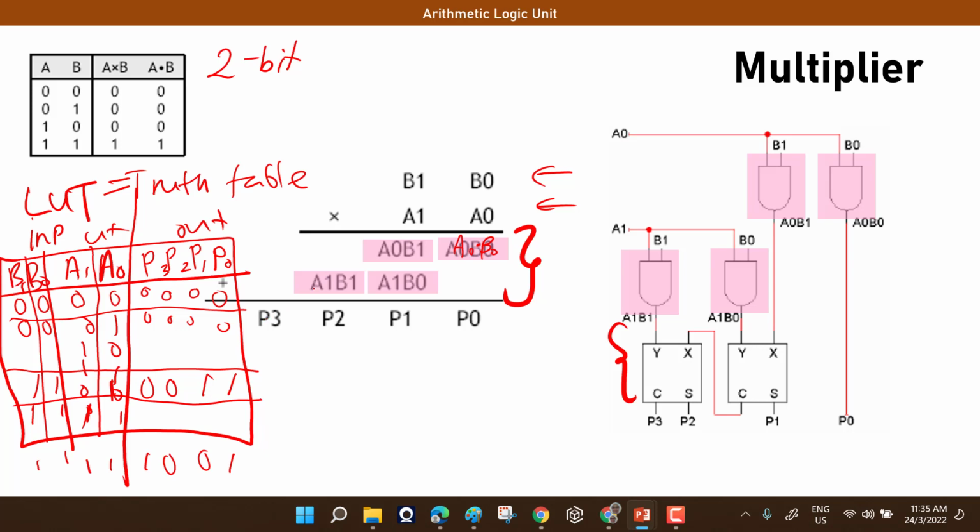Okay, ma'am. So, like this. When you want to execute a multiplier or adder and so on, there are ways of doing it. One is by implementing a circuit. So how do we implement the circuit? By taking this mathematical process and transferring it directly into mathematical gates. Another way is by using this lookup table or truth table. Last time when you learned digital electronics, once you had derived your truth table, the next step is to design a Boolean circuit. Before getting to the circuit, you had to derive the Boolean expression.